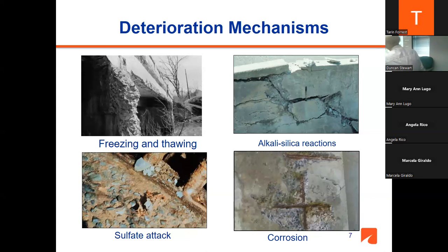The next one here on the right is the alkali silica reaction. This is a median. And as you see, I took that picture. You see what happened to that concrete because of a reaction between the siliceous aggregates, some of which are more reactive than others, and the alkali, which is mainly coming from the cement. It forms a gel, and that gel expands. And then sulfate attack. The sulfate works with some of the hydration products in the system and causes calcium sulfoaluminate, which is an expansive product. It needs space. It doesn't have any space, it's a rigid system, so it cracks.